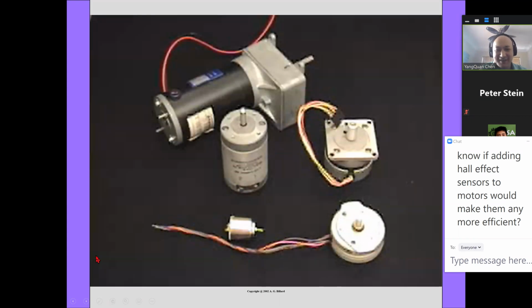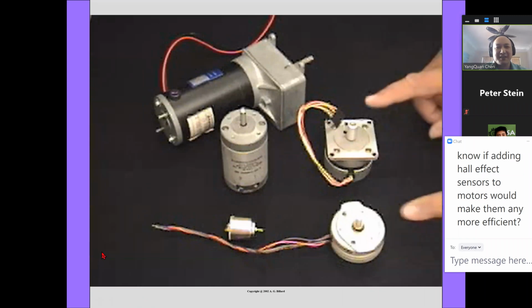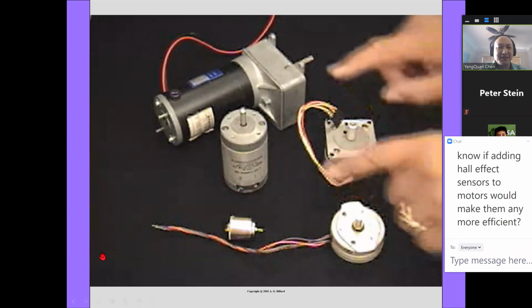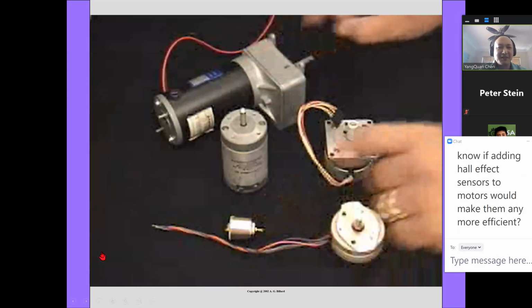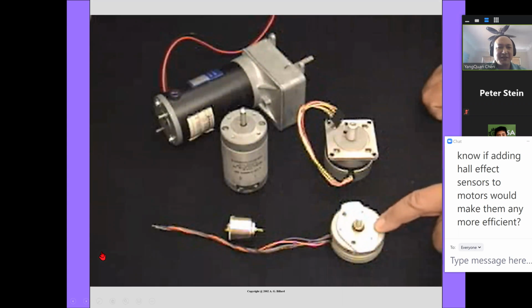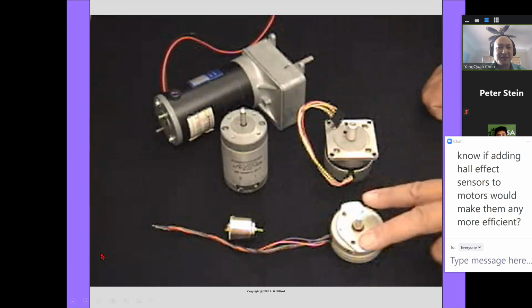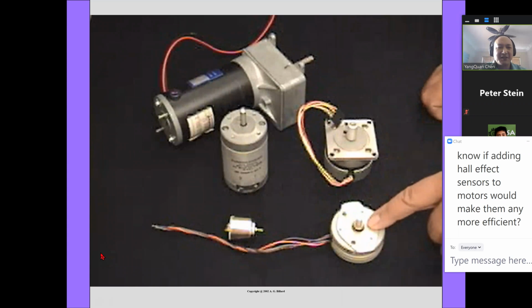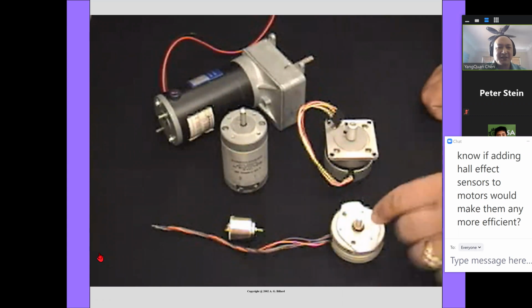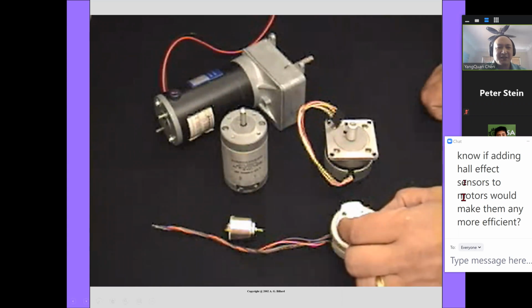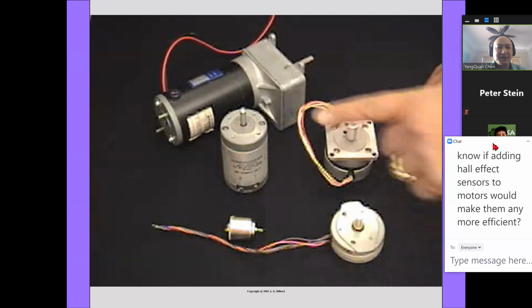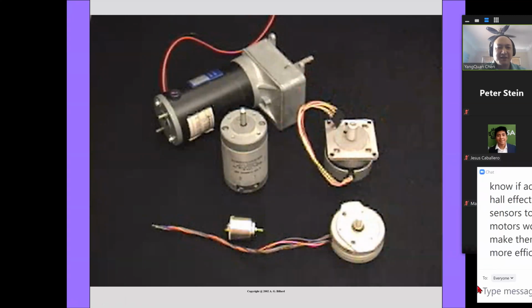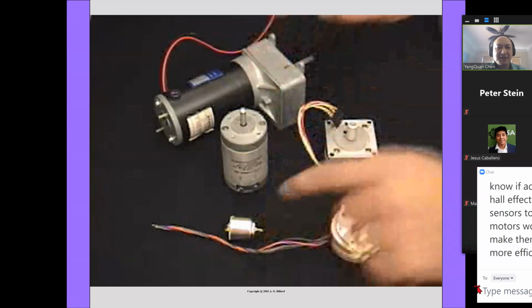There are two primarily different types of DC motors that we use in our mechatronic designs: stepper motors and permanent magnet DC motors. The stepper motor is also a permanent magnet DC motor, but it has the interesting capability that it will move in a digital or incremental rotation rather than continuous motion that we obtain from the DC motors.